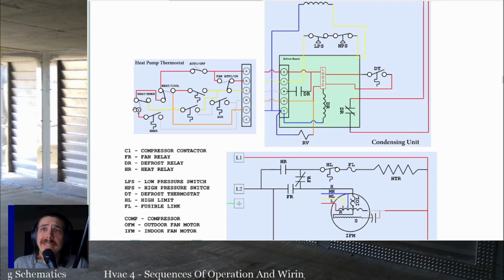We also have a heat or emergency heat selector, and that's going to dictate whether the outdoor unit runs in heat or whether you only power the emergency heaters. If we set the thermostat to cool, then you can see that it's going to automatically power the O wire, the wire going to O, which is going to keep the reversing valve powered until you switch operation.